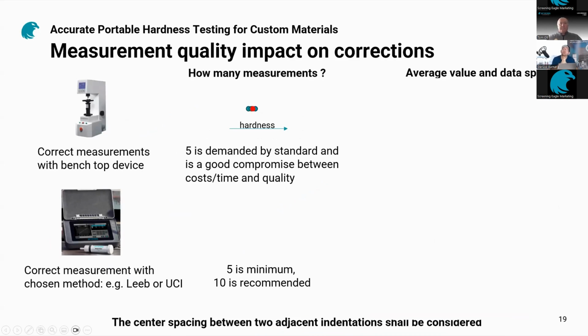If everything works fine and you carry on doing further measurements, the average does not change. But it is generally good practice to have higher statistics, because it might happen that additional measurement points are going to change your average. So the conversion you would be applying to your material, and perhaps, let's say, to a production line measuring different materials, will be simply wrong.